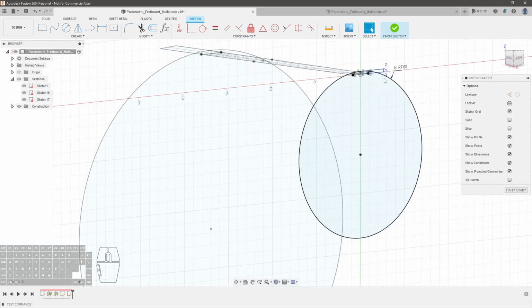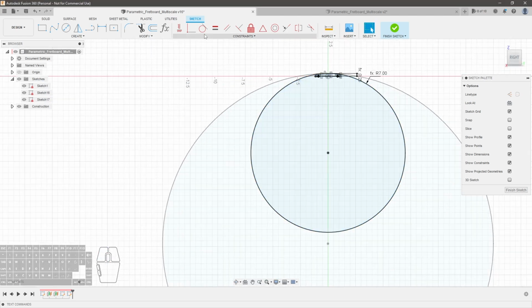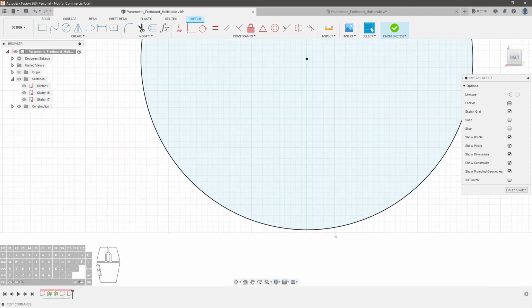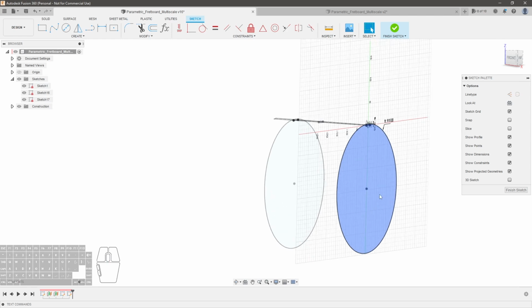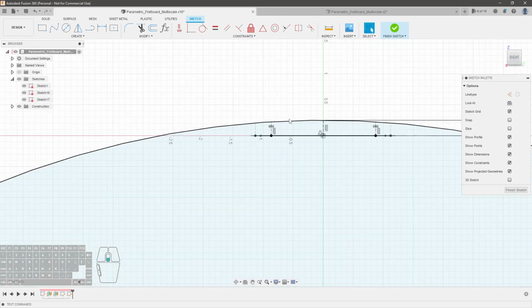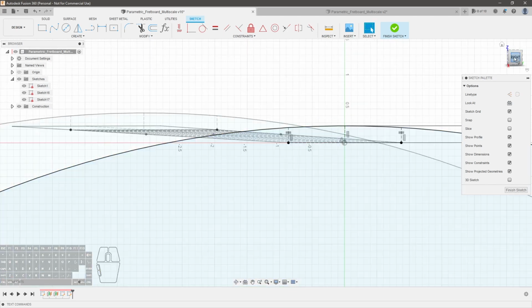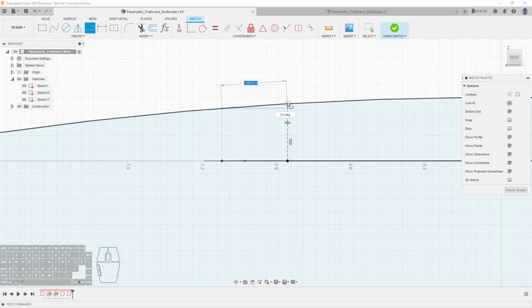So right now we have a 7-inch radius at the nut, and I believe it was a 15-inch radius at the heel. So if we look at it from this way, let's change this real quick to be identical to each other. So fretboard radius nut will be 15 inches. You'll notice that we have two circles that are directly on top of each other, and basically what we have is a cylinder rather than a cone. So if you made these identical radius, you could have a single radius design. And so it would be consistent all the way, consistent thickness in the middle all the way from the front to the end. But what you'll notice is that there is a slight taper from here to here, right?